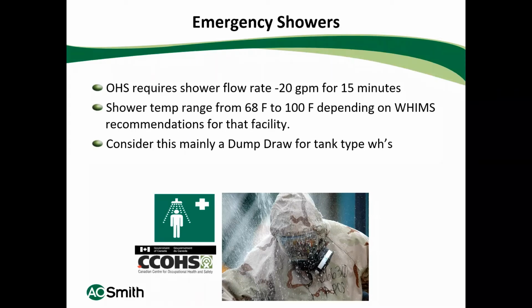So one facility may require 70-degree Fahrenheit water, whereas another facility may require 80-degree water, or some 100. I'm going to run through some of those examples and show you my methodology for how I determine what size heater. I also wanted to say that I would consider emergency showers mainly a dump draw, so most of it is going to be in storage.